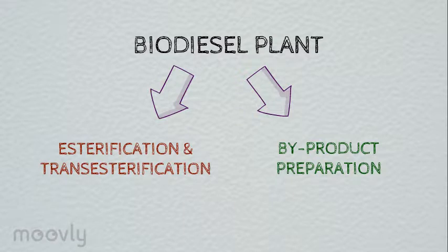The distillate represents the high-quality methyl ester and is transferred to the biodiesel quality tank, and later to the biodiesel storage tanks. The low volatile high boiling substances are removed in the distillation unit. Low volatile high boiling substances, namely bioheating oil, are discharged to a storage tank. It can be further used as heating oil for an oil burner and will be used to provide process heat in the plant.